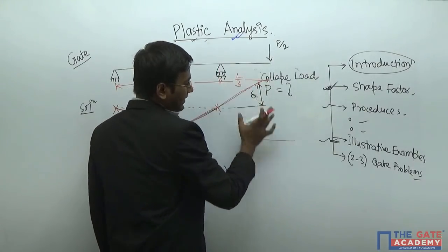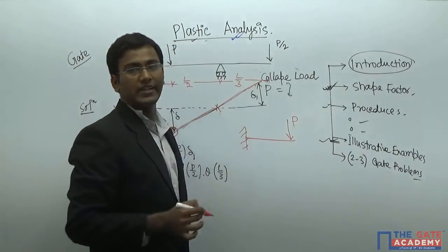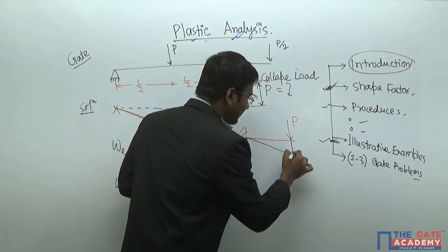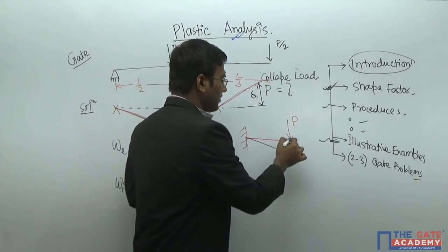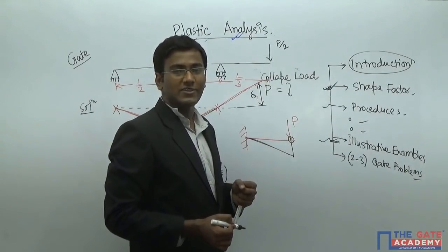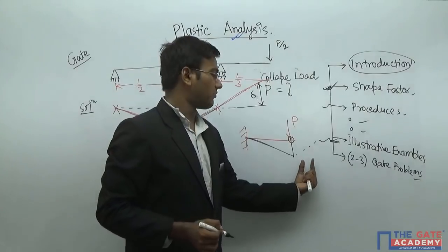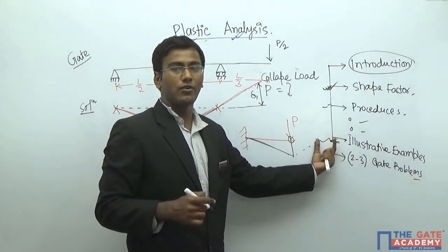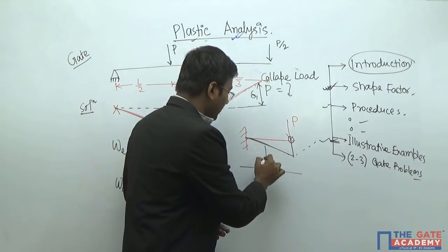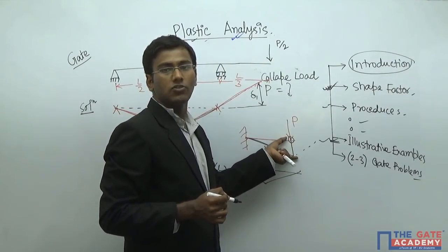This is a cantilever portion like this side, right? We are providing a load at a free end. In this case, there will be a deflection like this, but there will be no plastic hinge formation here. The question is why? Because if there is plastic hinge formation in this portion, there should be some remaining portion of the member this side. What do we mean by plastic hinge? Just take a simple member. A hinge has been created. If I apply a load here, it will deflect like this. It is a deflected shape. It is not a plastic hinge shape.